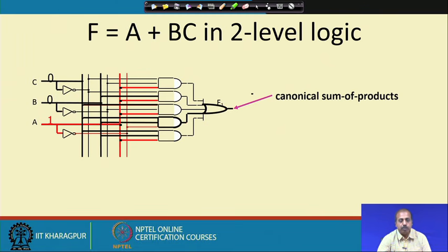So, this way, if you take these gate delays into consideration, you may find some behavior of these circuits in some intermediary form. So, that is not stable actually. So, in between it shows some glitch. So, that can happen. You can just trace through this circuit to see that this is changing the value.